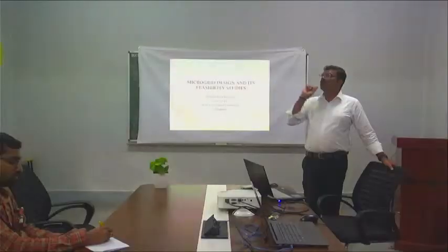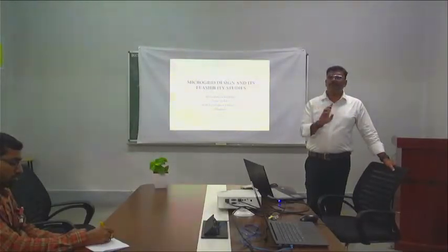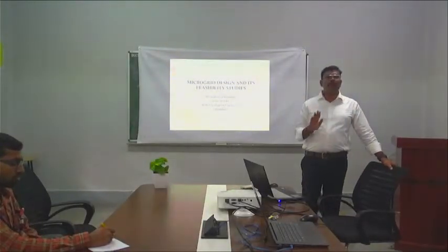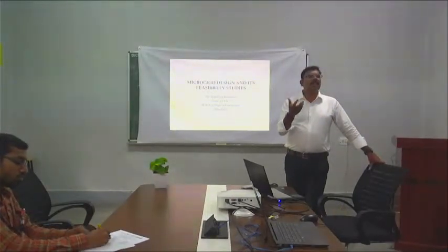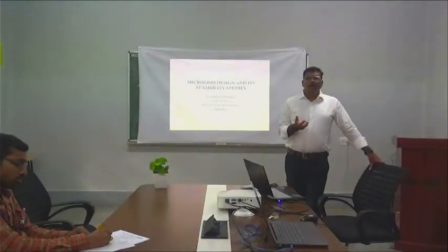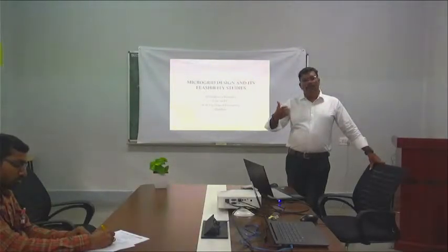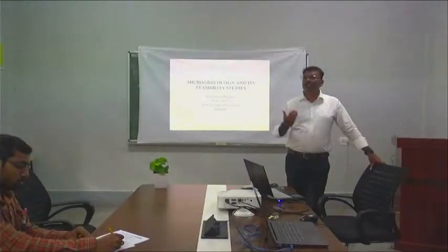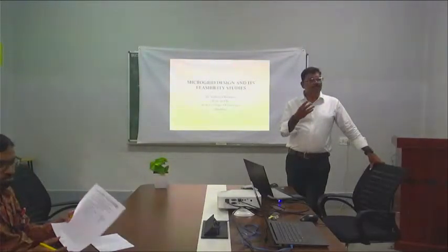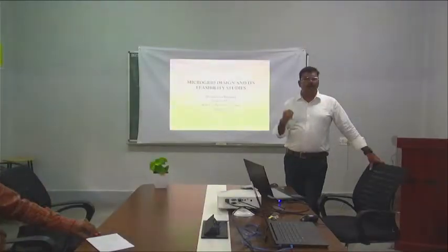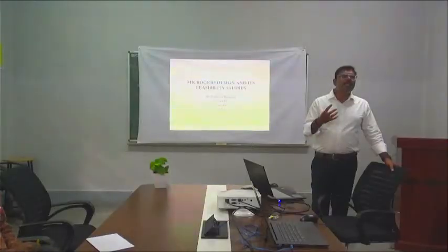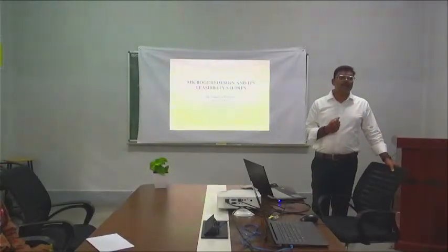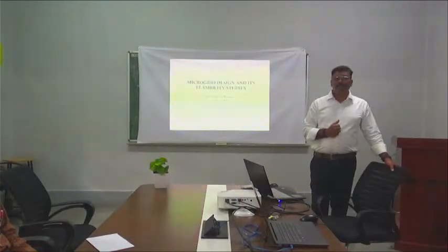Suppose this is the area of the room. In this area we want to develop one solar PV system. What are we basically going to do? How much yield will we get per annum? First we need to analyze. And when you install, how long will the payback period take? All these analyses can be done using PVsyst and HOMER. The disadvantage in PVsyst is that we cannot integrate multiple energy sources. Suppose a wind turbine is not available and only solar is available, a diesel generator also cannot be integrated.